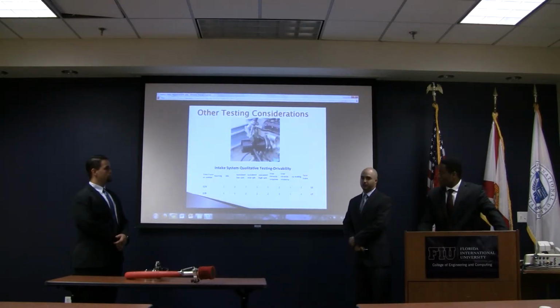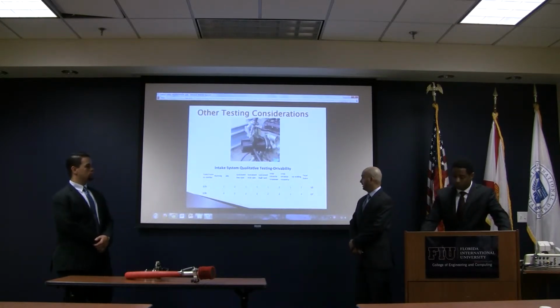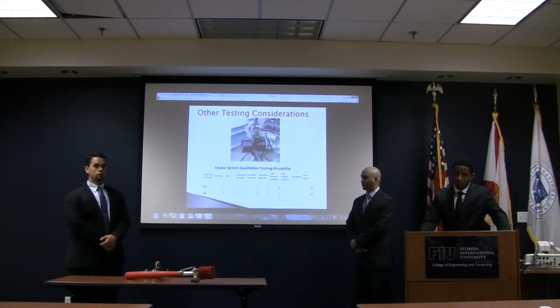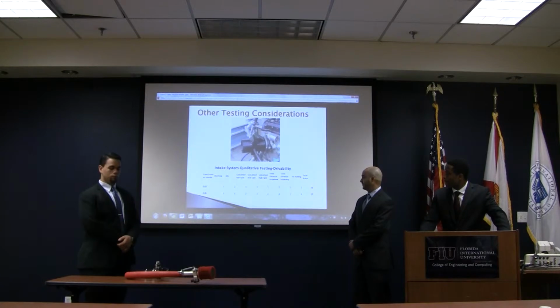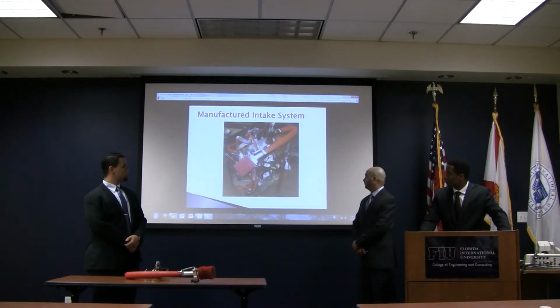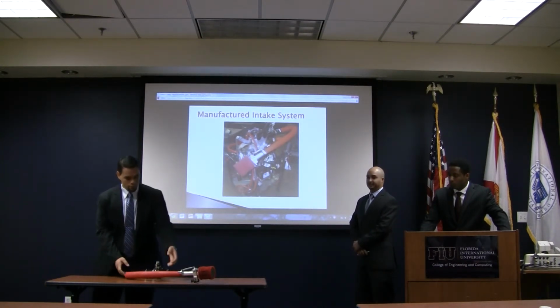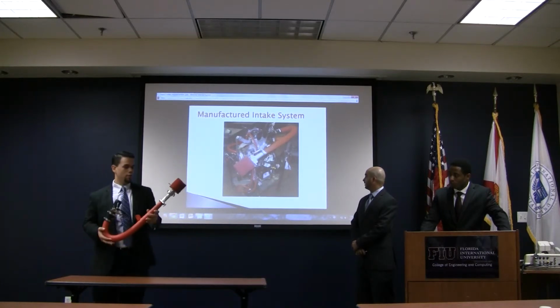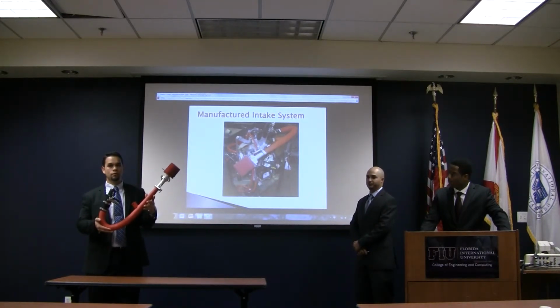We also looked at a qualitative aspect of our design and developed a simple scoring sheet to look at basic drivability parameters. The intake system was manufactured using additive manufacturing processes. The intake plenum was made using selective laser sintering, while the fuel injection module was made using fused deposition modeling techniques.